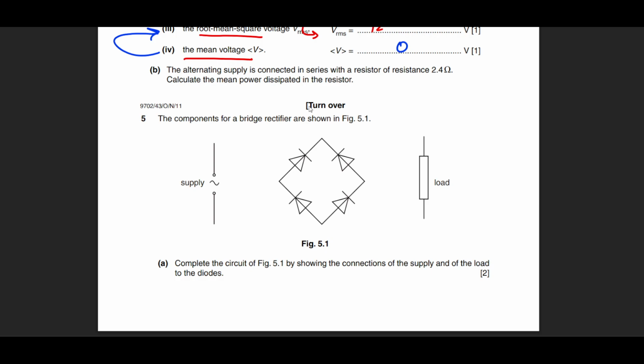So let me give you the solution. Now the problem is, if you had started from this point, let's say by mistake, then you can see that if the positive current was coming in, it couldn't go there, it couldn't go there. It cannot go anywhere. So this direction of connection is not right. So if you're trying the hit and trial method, what if I connect this first terminal over here? Does my positive current have somewhere to go? Yes, it can go towards this diode, while this diode will reject its path.